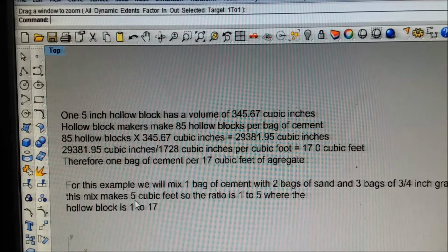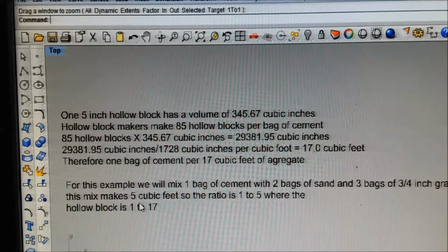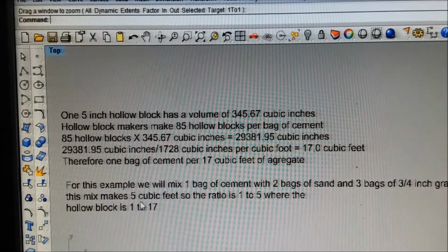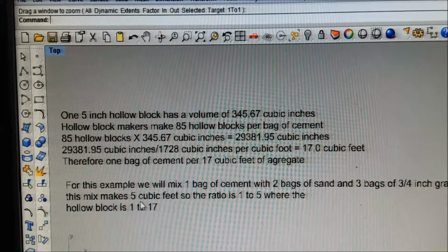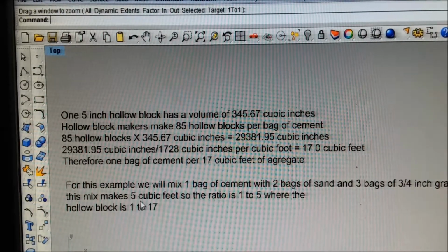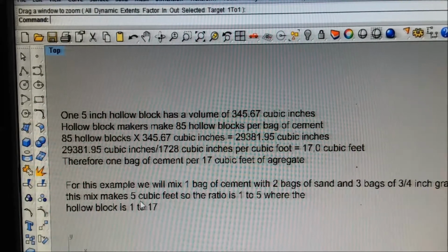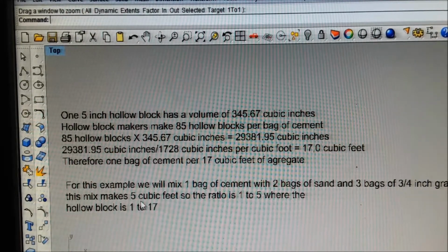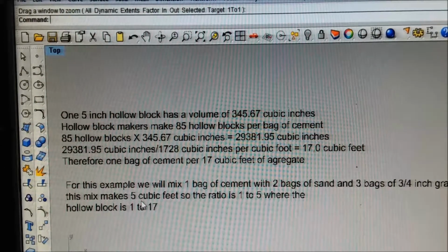The way we fill our bags, we tested the amount of cement in a cubic foot bag and into a test box, and then we filled that box with sand and put it in a bag, and gravel in a bag, and that was our standard from then on. So we tried to make our sand and gravel this 1, 2, 3 mix.